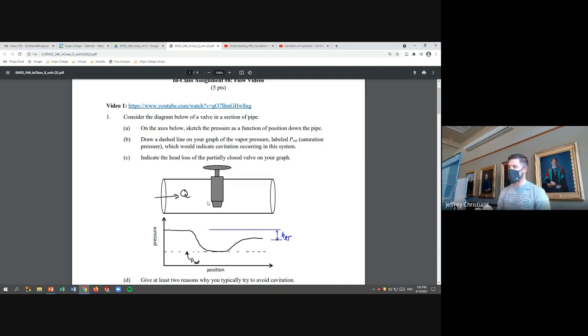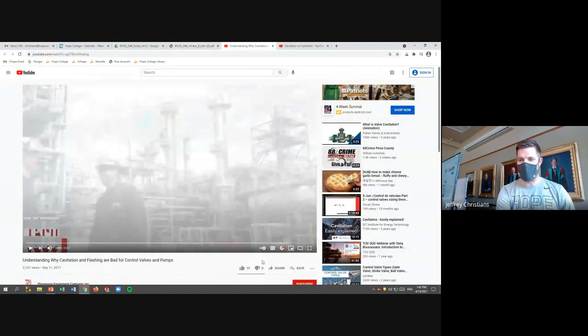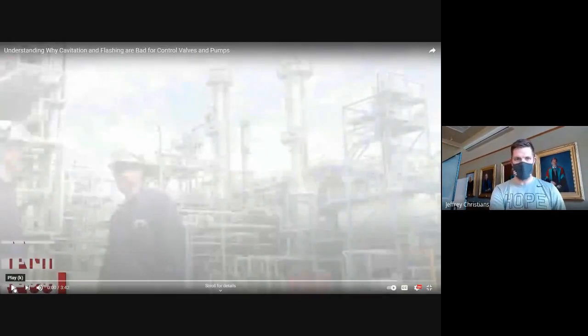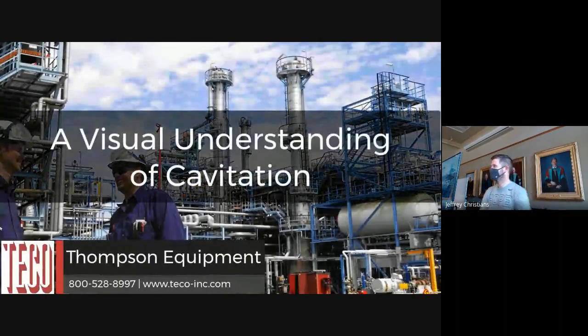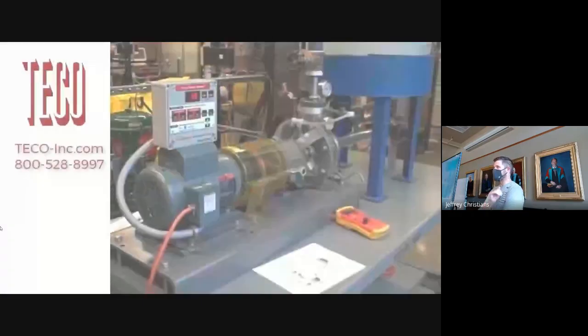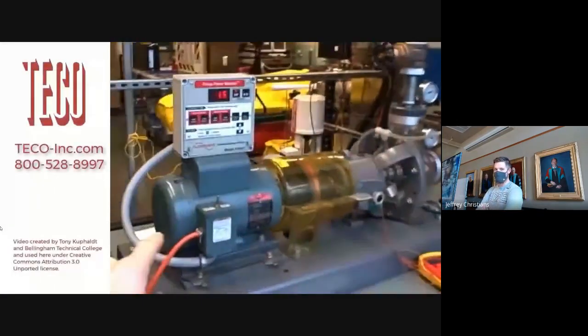You don't go up in temperature, but your pressure gets so low that you actually have boiling in this valve. It's an effect that we call cavitation. We're going to watch this short video mainly because I like the music, but I think he does a good job describing cavitation.